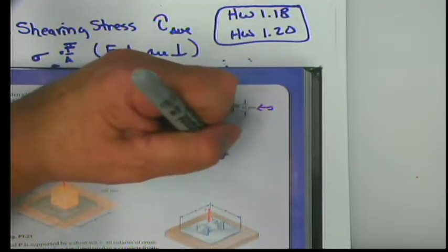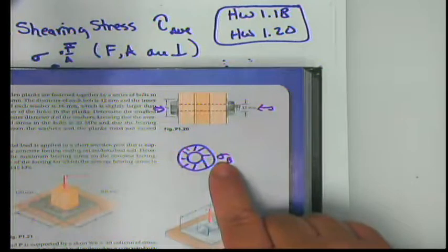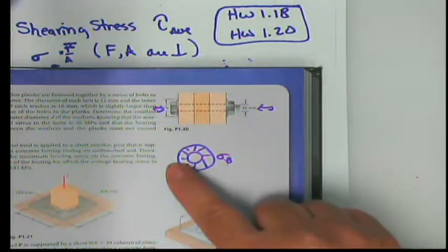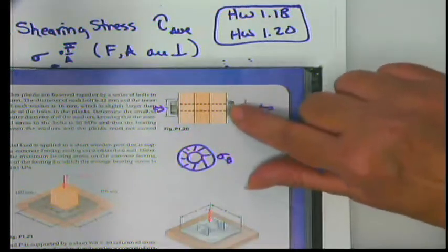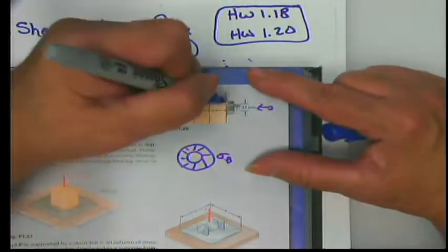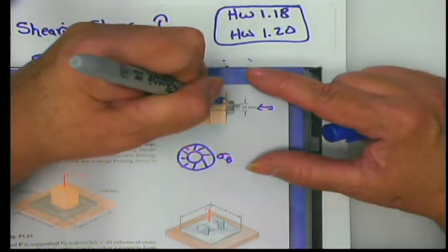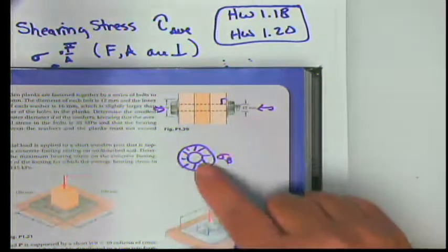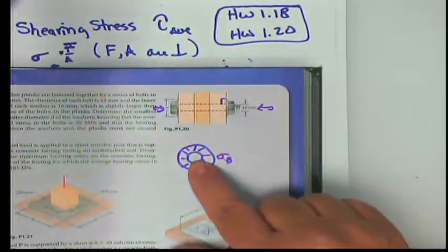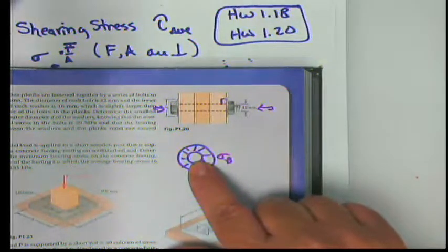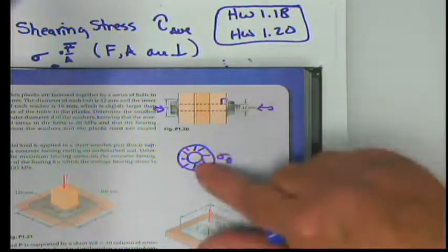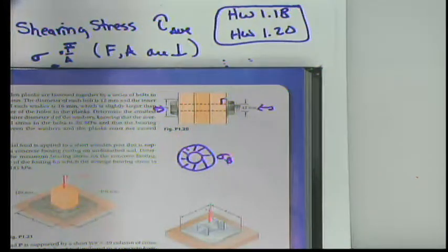It's a different kind of normal stress, really. If it fails here, there's just this piece. The bolt is inside, the washer has some outer diameter, and you're going to fail on this circle with a hole cut out, an annular circle is what it's called. That's going to be the area which it fails.